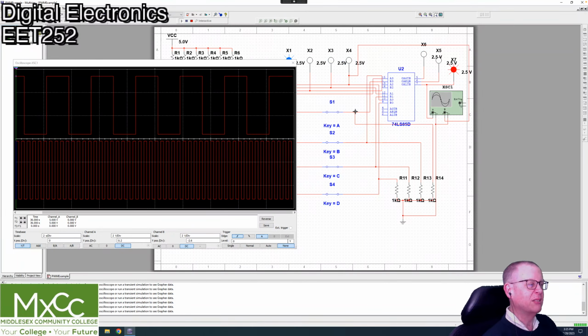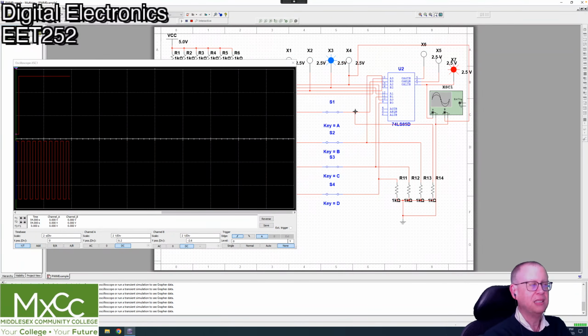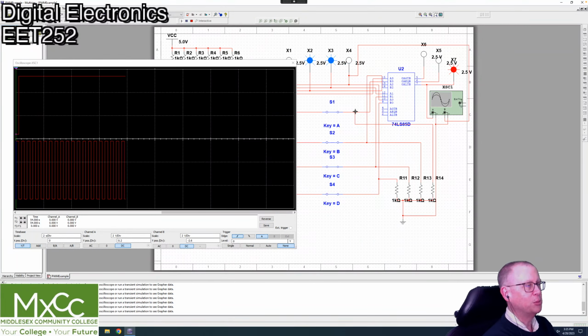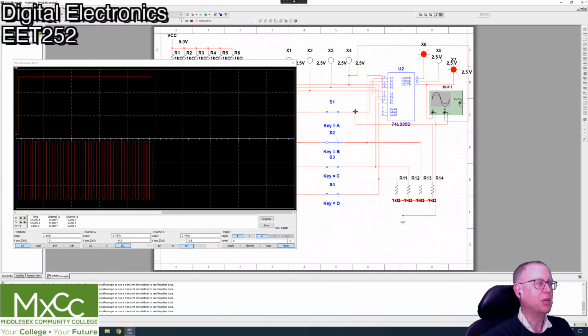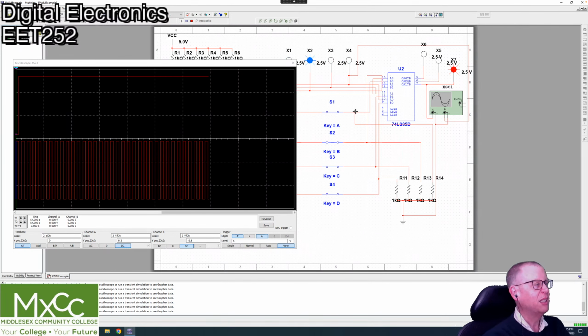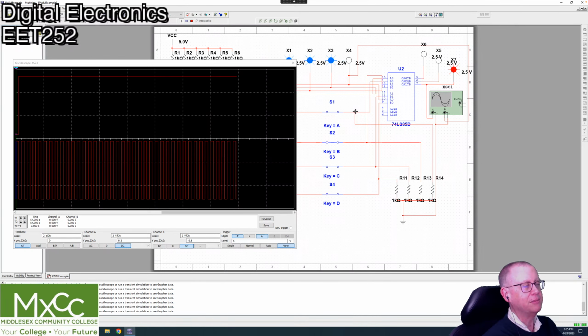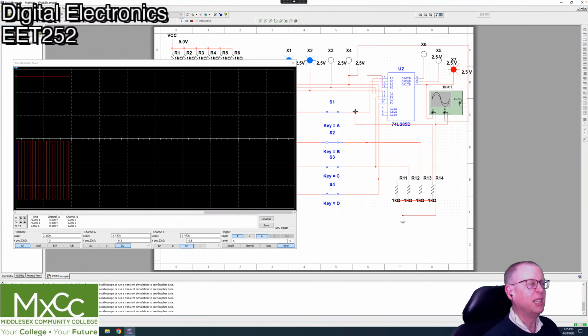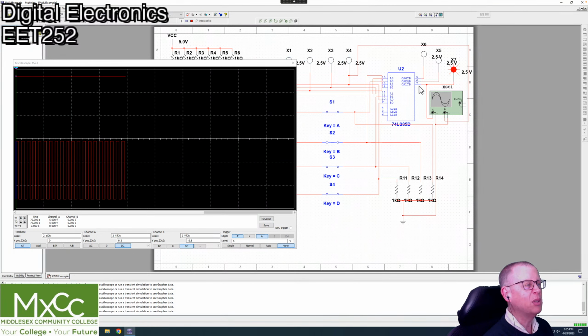And then I can close all of them, and now maybe I'm getting all high, because maybe my number 15 can never be less than the count, which only goes up to 15. I'm using the A is less than B output on the device, the 74LS85.